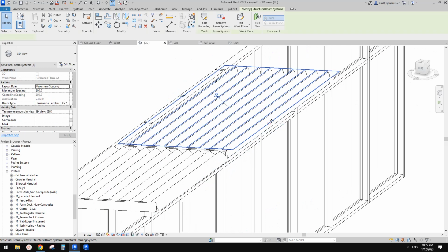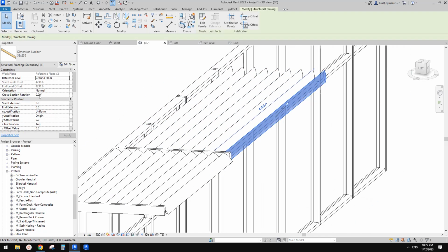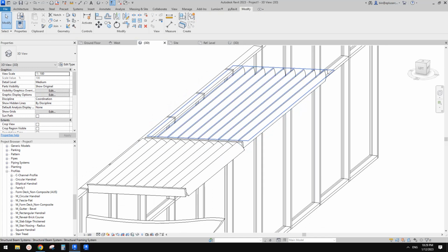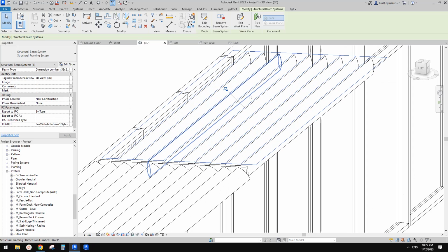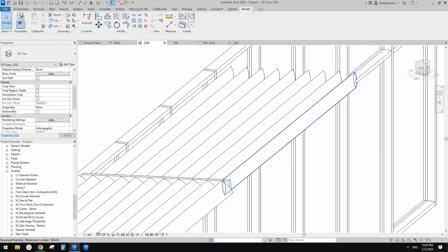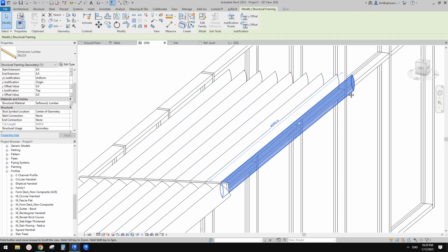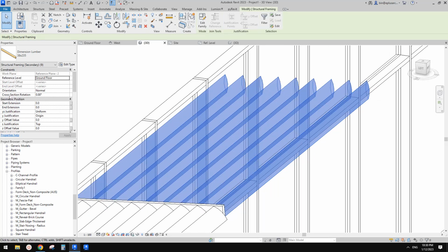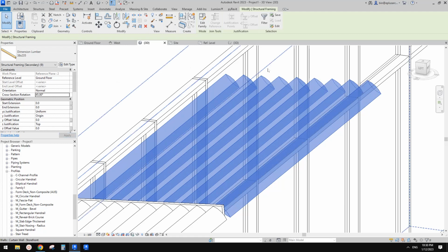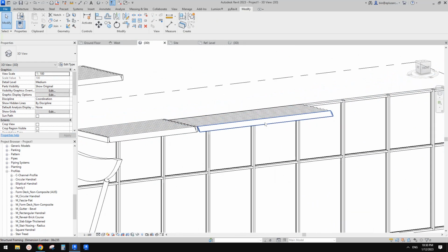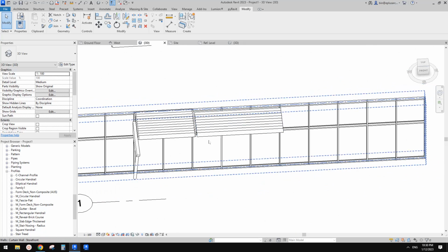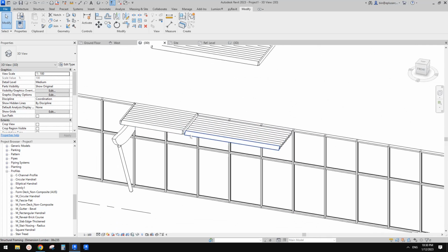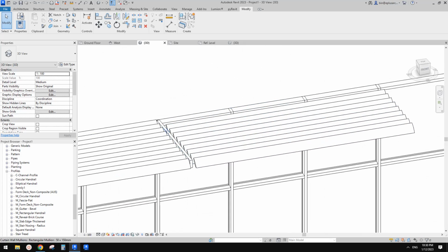And of course, let's see if we can change the... I think we can, right? So we already see that parameter there. So it's not under this beam system, but for individual beam. So you can select one, type SA, select all. So I think you have this option. Okay, so typing 45, that's it. So this is another option. So if it's flat, you can also use beam system. Okay, so very similar. Looks like okay.